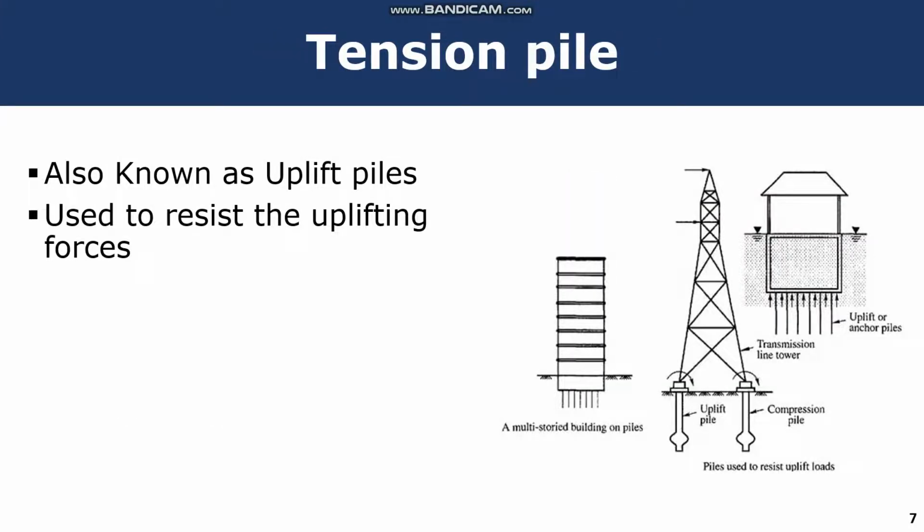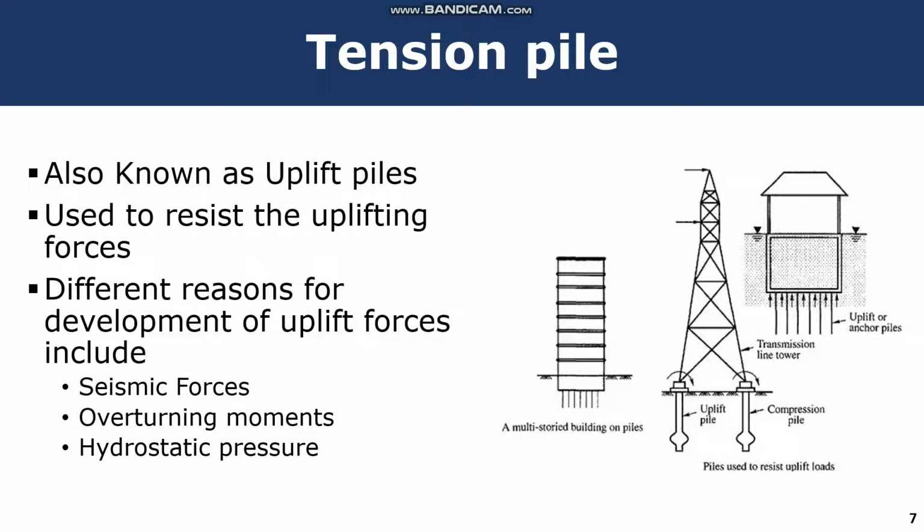And when we talk about tension piles, these are also called uplift piles. If you look at the figure on the right, the one on the left-hand side is an uplift pile. When the lateral load of wind acts on the top portion of this structure, it will try to uplift the structure from its base. So this uplift pile will resist the structure from lifting. It is resisting the tension force created due to the lateral action of the winds. So it is a tension pile which is utilized to resist these types of tensions.